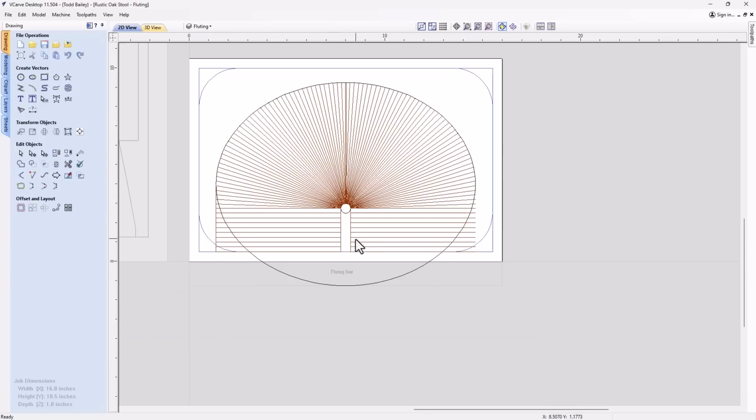And now I have everything I need to go ahead and create my fluting toolpath. Now, like we did in the sample, I could go ahead and reverse the direction of every second one that's here, but that would take a little bit of work. So actually all I really want to do is just select all of those vectors in the order I like them to cut in. I'm not going to worry about the time saving right now, but if I was going to mass produce these, then I probably would want to worry about that. So let's go ahead and do that.